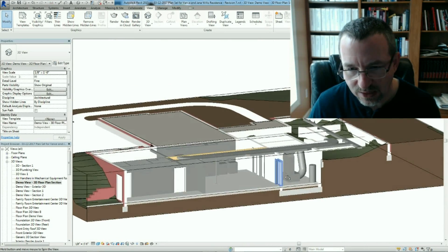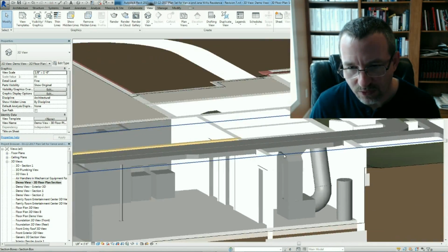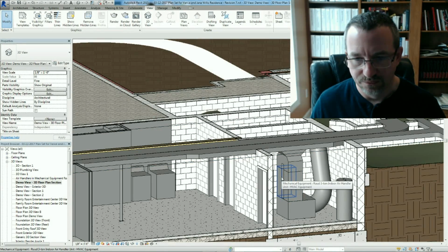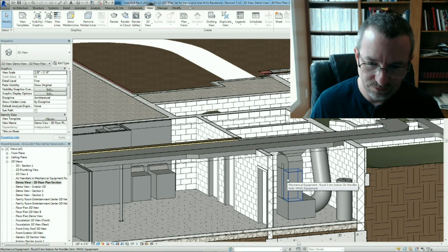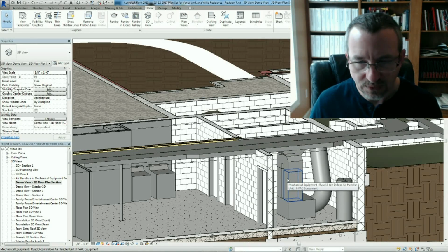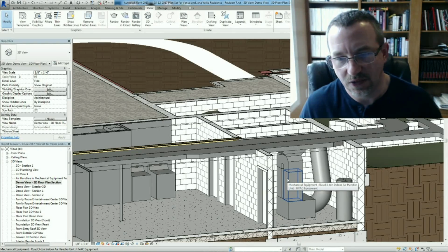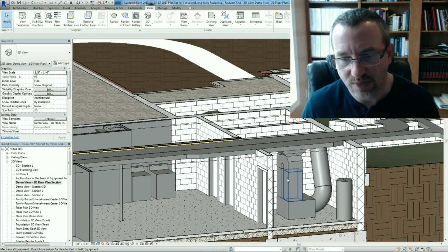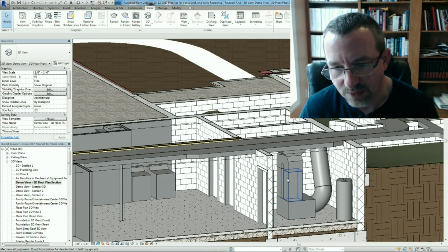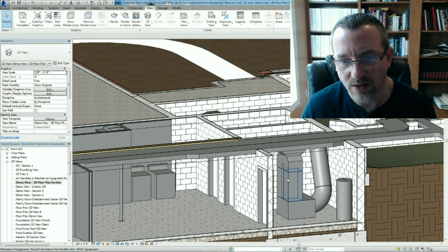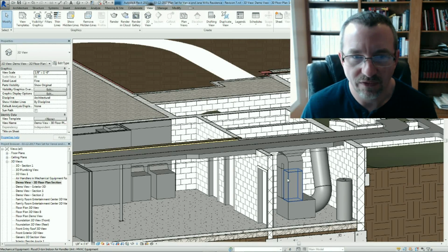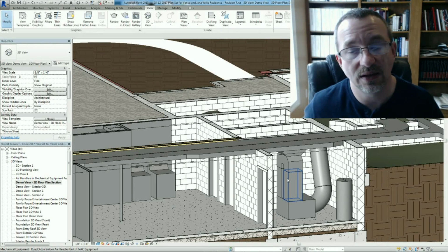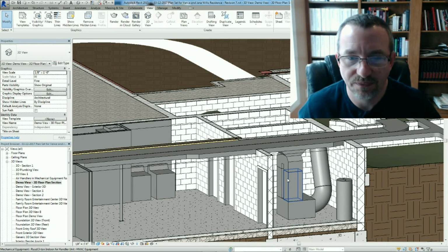One of the things I did that was pretty cool is I've twinned these two air handlers together. So it's not like one heat system heats one part of the house and another system heats another part. They both do both. Or they both do the whole house is the best way to put it. The way that's done is they are staged. So both of them are heat pumps. Each of the two units that heat and cool my house is a 3-ton electric heat pump system.